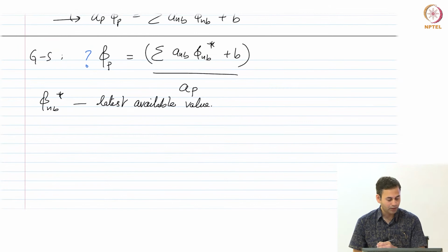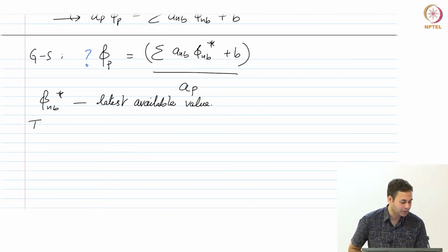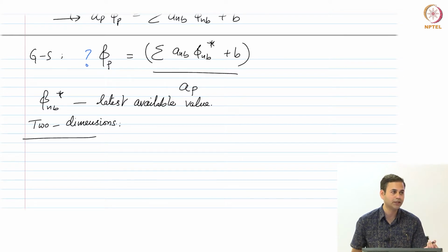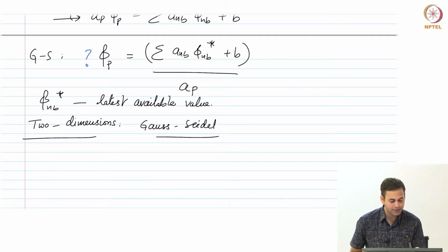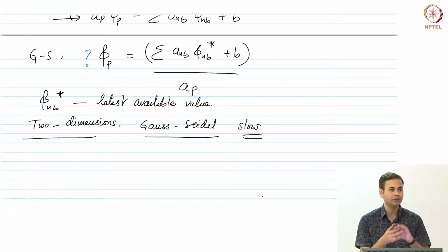All right. So, then this is the concept. Now, let us say, how do I now extend it to 2 dimensions? Of course, in both 2D and 3D, you can have Gauss-Seidel as it is. Okay, you can still apply Gauss-Seidel. Only thing is that it will be kind of slow, because the information only propagates by one cell per iteration in Gauss-Seidel, right? Because you have one sweep in which the information goes from one P cell to the E cell after the end of the iteration.